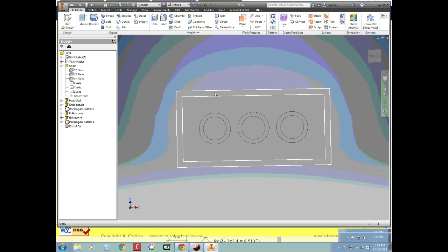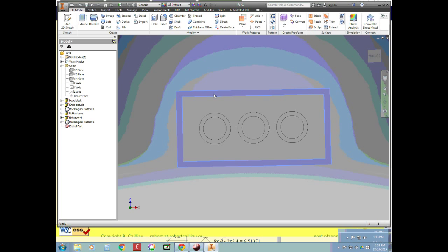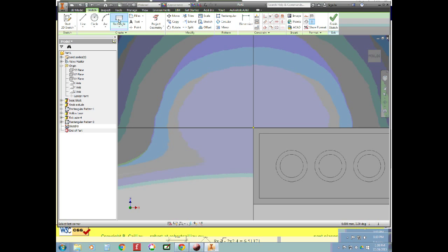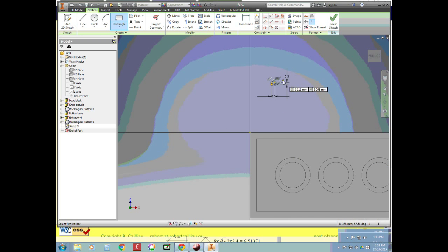So once again, we want to right click on this and choose new sketch, and we're going to use the rectangle tool, and up here I'm going to make it 0.6 wide, tab to go to the other dimension by 0.3 tall, and again it has all those constraints turned on. I don't want to see those, so F9 will turn them off. And then oh, we're already out of the rectangle tool. That's good. Now we need to dimension, or we need to locate this. So I'm going to bring it down here onto our drawing.